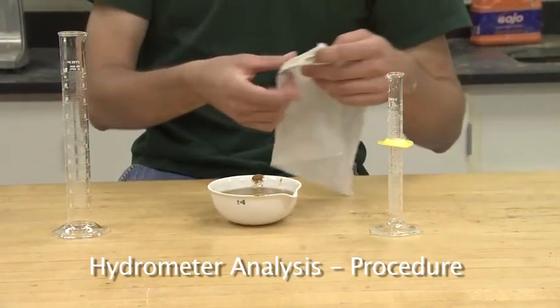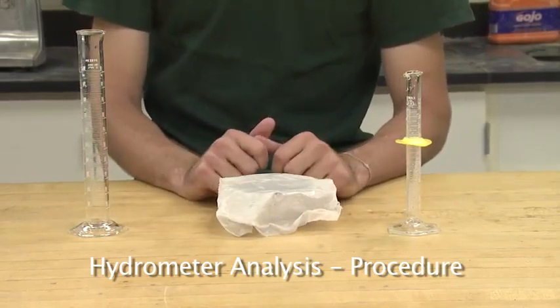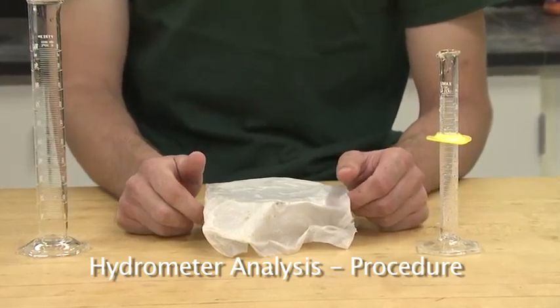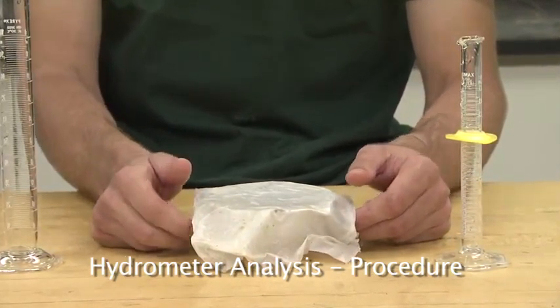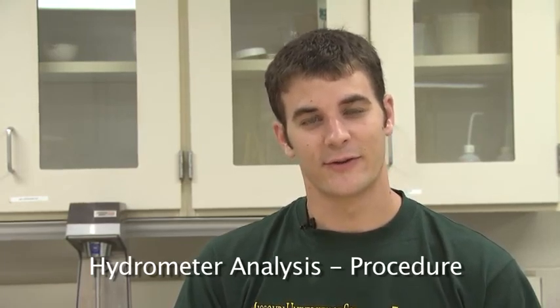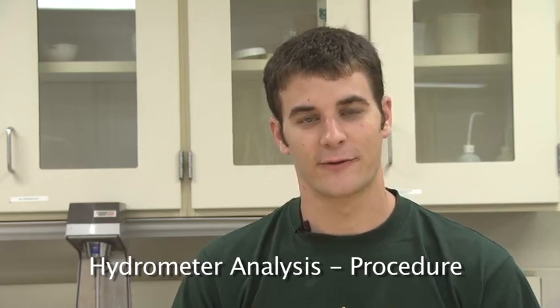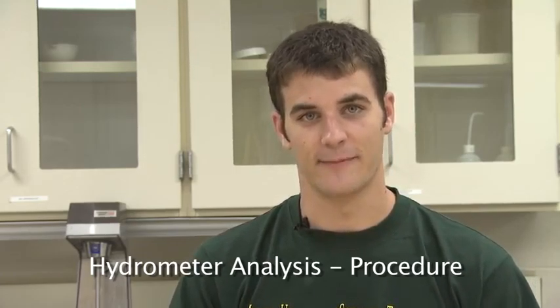Cover with a wet paper towel and allow to stand for 15 minutes. The sodium hexametaphosphate is similar to laundry detergent. It works to break down the cohesion between the particles so that the individual particles will not stick together. Note, this is a deviation from the ASTM standard. ASTM suggests that you let this set for up to 24 hours. We will only let it sit for 15 minutes in the interest of time.